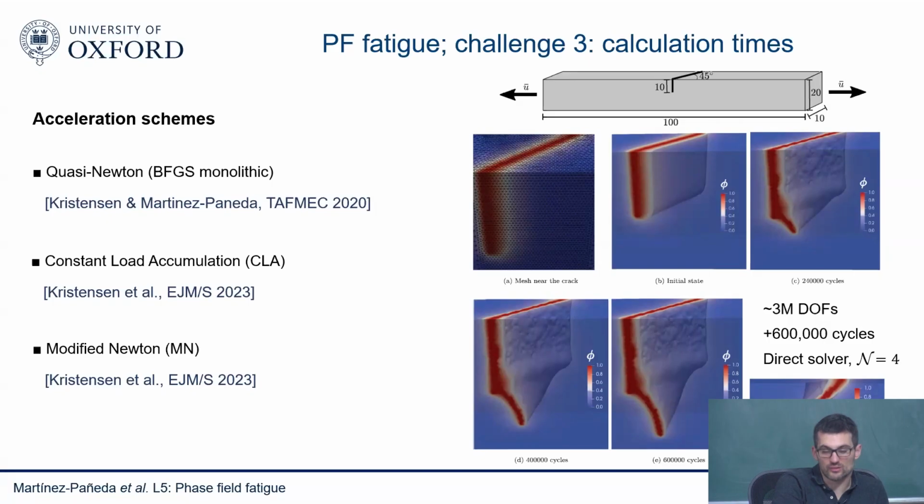Yeah, to a certain extent it's true. But if you think of an SN curve, when you are accumulating cycles in the lower regime, everything is quite elastic. But then you need a model that captures that when you get into plastic deformation, you accumulate damage in a different way, because you're going to have some hysteresis effects and a different behavior.